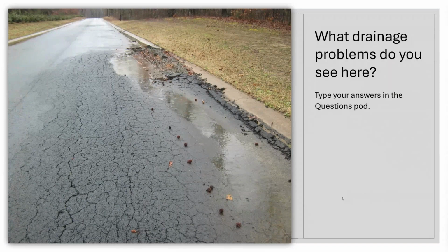And that's principle number one that we don't want to have. You don't want the water running to the roadway. You want it going somewhere else. So we're depending on this roadway essentially to be a drainage channel to catch all of that water. And even though we have curb and gutter, theoretically, it's going to run down over to the edge, move to a drop inlet, and be gone. But that's not actually happening because we're asking it to do too much. So, yeah, that's probably about all to say on that.